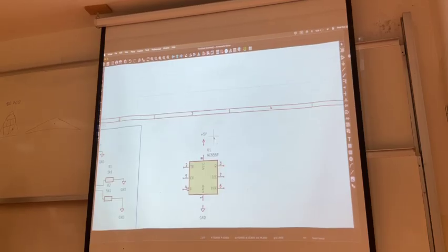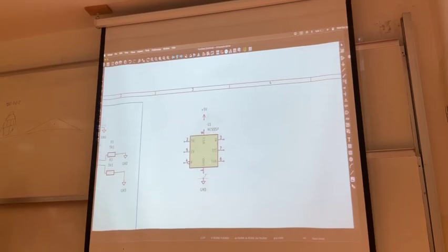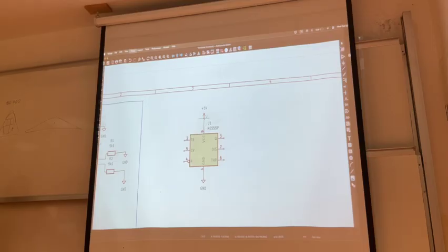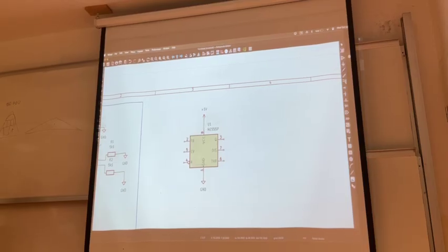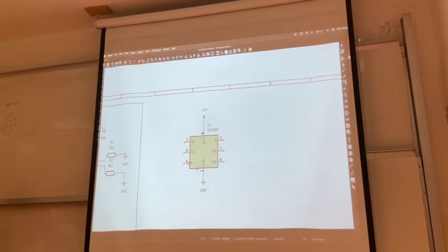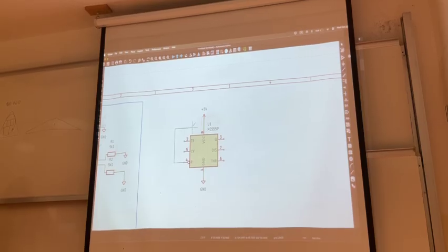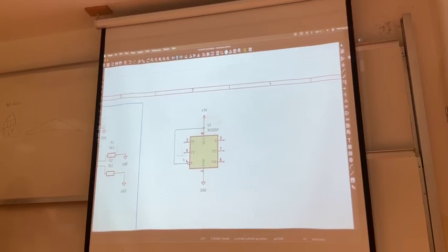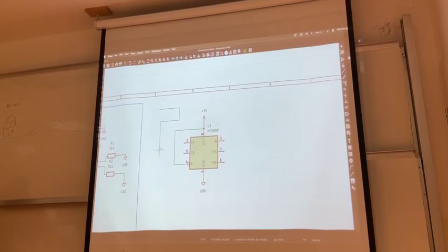We can start on the thing right now. I wire them like this. This 8 pin is the VCC. This is the ground. I put the reset pin to here. I do this curving thing by doing. Click on W. Click on mouse 1. Click on mouse 1, so I can snake around like this. Okay?